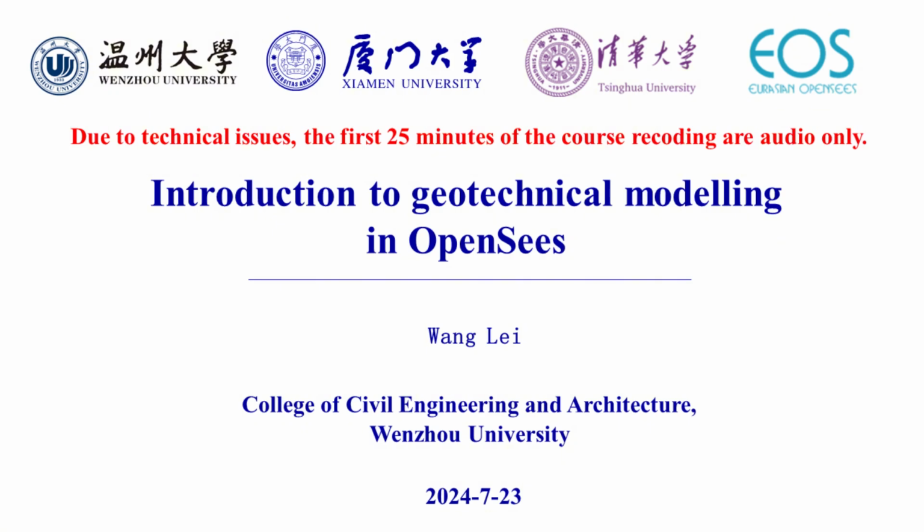That is because for nodes 16 and 34 we have already used the fix command to constrain the DOFs. When you use fix and the DOFs are fixed, it means that the memories of the DOFs in OpenSees have already been deleted. So if they are deleted, then you cannot use the equalDOF command here.